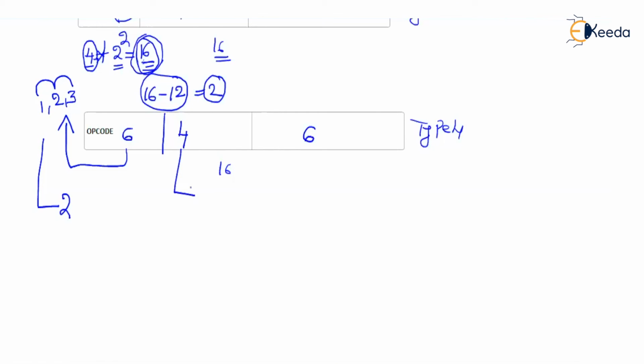But in the next 4 digits, each and every combination is available, right? Because this is the first time we are using these 4 digits for an opcode. Earlier, these 4 bits were a part of some operands. Now this is the first time we are using these 4 digits in the system for opcode. So these 4 digits are never consumed, not occupied for an opcode. Total combinations in these 4 digits are available.